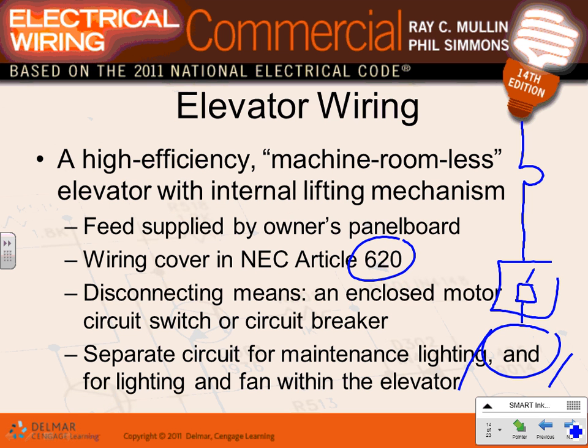Can I have thumbs up, Chad? How do you size the pump? It's a horsepower, right? Say if it was a 50 horsepower, I hope, guys, you know how to size a branch circuit for a 50 horsepower. We all know, right? 125 percent times the full load current, plus the fuse and the circuit breaker: 175 if it's a dual element time delay fuse, 300 if it's a non-time delay fuse, 250 if it's an inverse time circuit breaker, and we size the whole system.